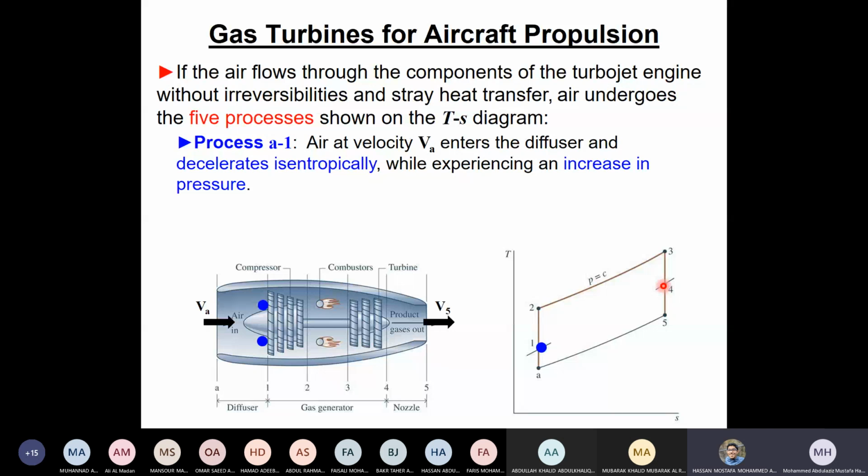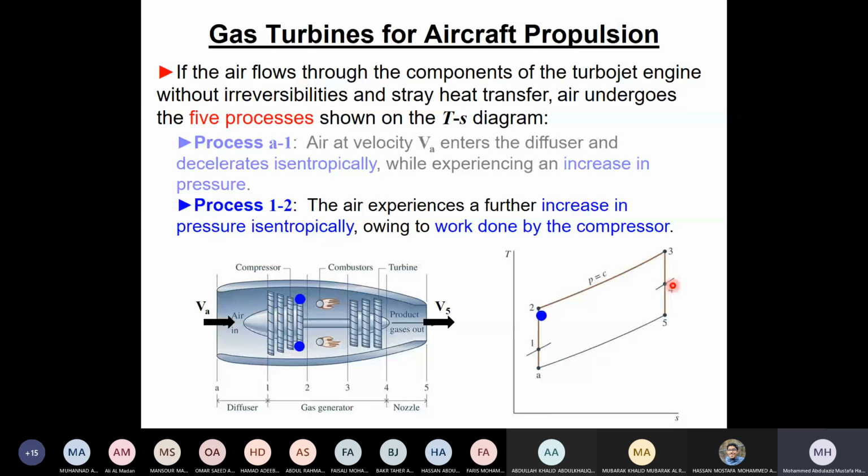Okay. So now, Doctor, a second question, yes, please go ahead. There is no need to calculate the enthalpies once the temperatures are calculated, right? Okay, it's a good question. Originally, the accurate thing is that we calculate the enthalpies: H1, H2, H3, H4. But when we say that Cp is constant, this is an assumption, we can consider temperature.